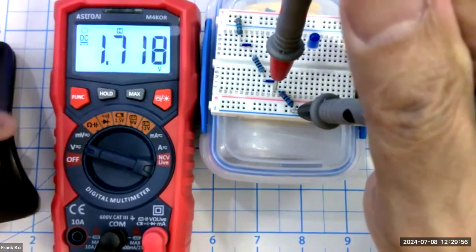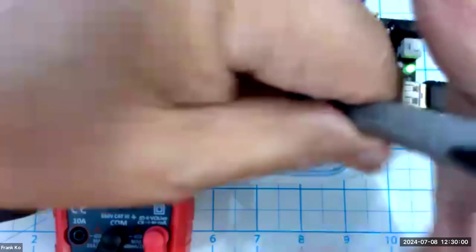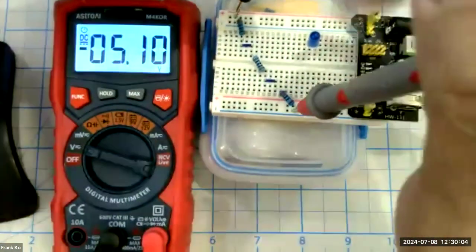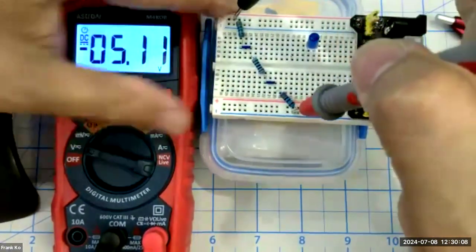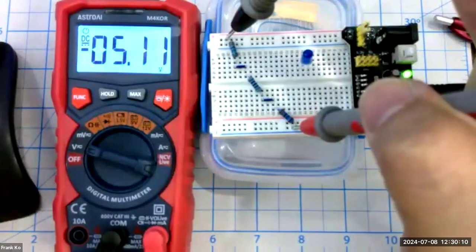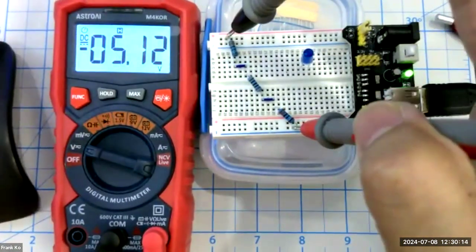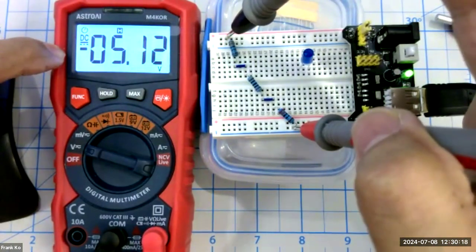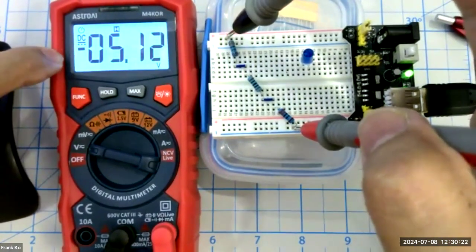So this is just a word to the wise, and I'll do one more. Very often, because we're in a haste to get things done, we might measure our total voltage this way, and we hope to get something close to 5 volts, measuring from one rail to the other across all 3 resistors. You press hold, you say, hey, I've got pretty close to my 5 volts, and then you realize, wait a minute, what's this negative sign? You have not done anything wrong. There's nothing wrong with negative voltage.